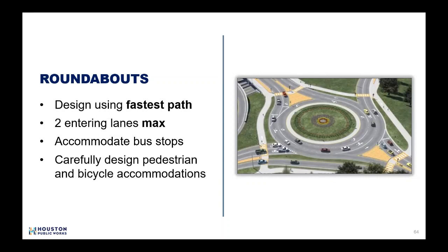Some of those concepts are, roundabouts first and foremost should be designed to control speed. A roundabout designer will look at the fastest path. Basically, all the other design elements fall out of the fastest path. So looking to control speed is the number one issue.